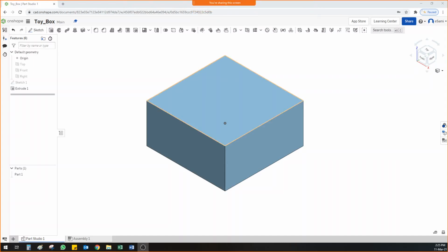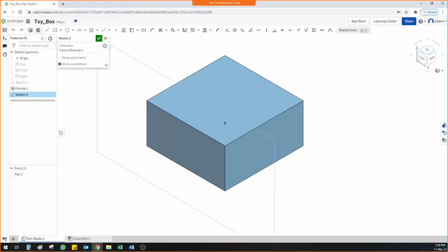Let's try to explore some more options here, how I can build another object after making the first one. So let's see if it is similar to SolidWorks or not. So what I will do is I want to sketch one tire here. So can I do it? By making two circles, I will choose this face and I will choose the sketch option on the top here. Here it allows me to make a sketch. So let's choose a circle and see if we can make a sketch here. Oh yes, we can. Okay, I'll just make a tire here and I'll just make another tire here.